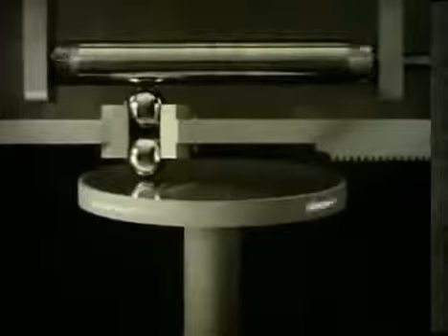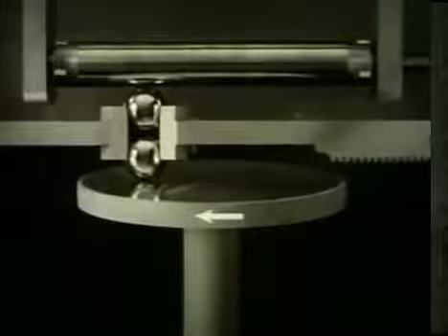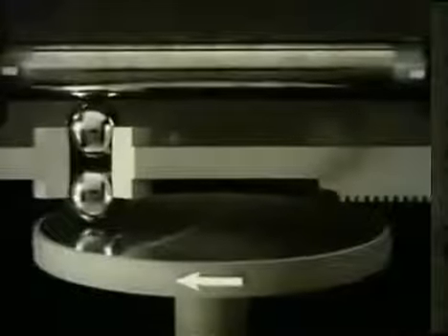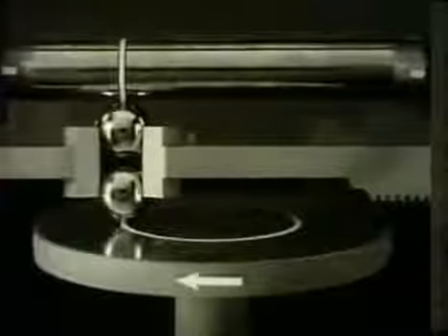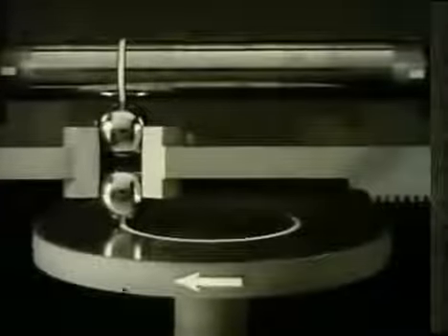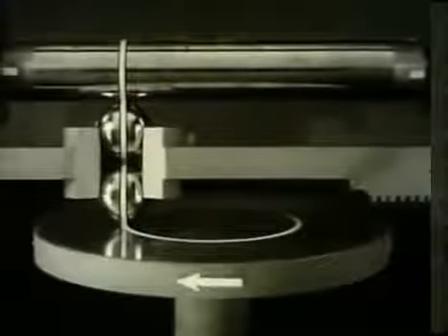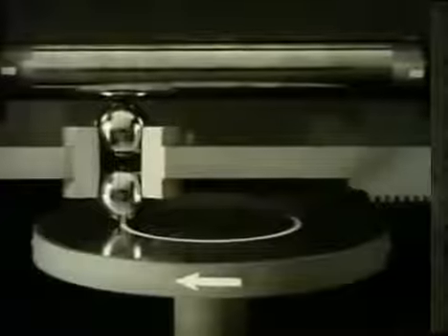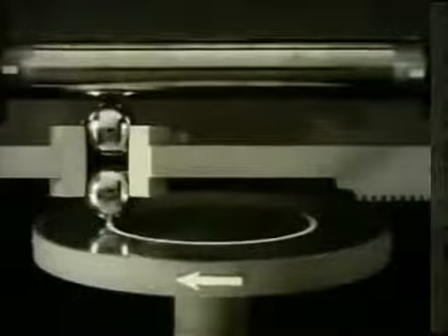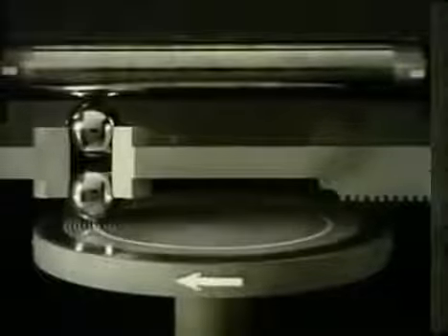In principle, the roller and disc are comparable to a variable gear ratio, where the circumference of the roller and the track on the disc act as two gears. The balls act as idler gears. The circumference of the roller and of the balls, of course, is constant, but the track on the disc is variable. This is the equivalent of an infinite number of gear ratios.